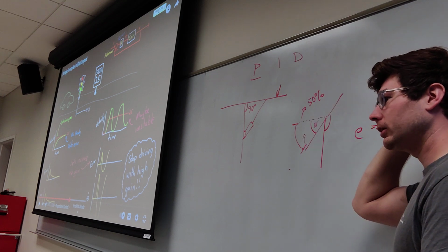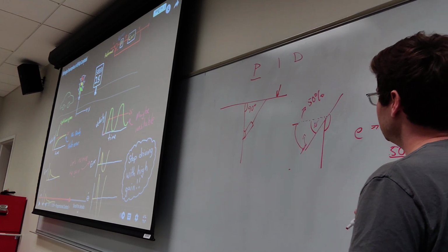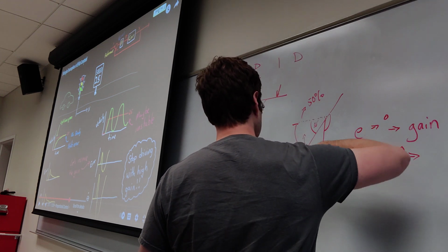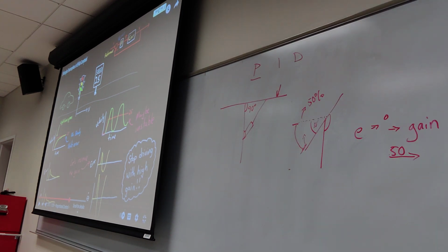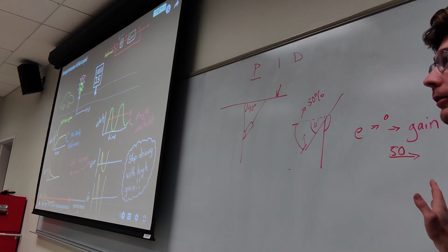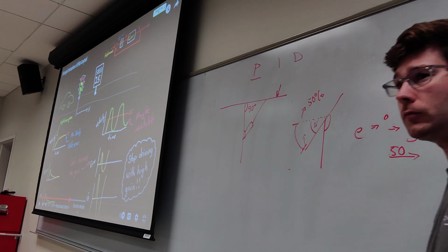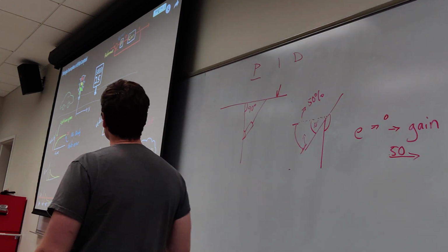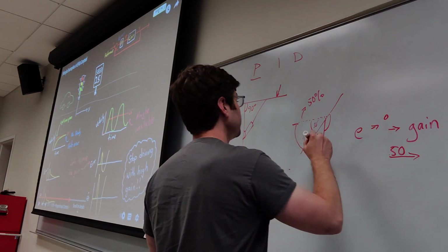It won't actually be a percentage, but you would have to essentially dial this in to give the right proportional response. This is, again, literally a proportional controller. If we have an error of this much, we're going to push this hard, as given by our gain factor, to correct it.